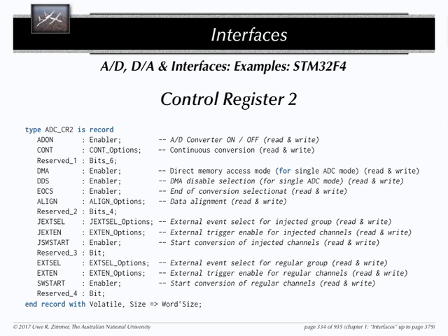You also see that the record now has a size associated with it. Here I simply use the information that we know how large a word is on my controller. So I say that this is a record which spans a whole word on my controller, and I also indicate to the compiler this is a volatile memory address. Do not do any compiler optimizations which assume that you can read this once and leave this in the register for further optimizations. You have to go back every time you want to read information from this thing to actual memory, meaning to the actual device.